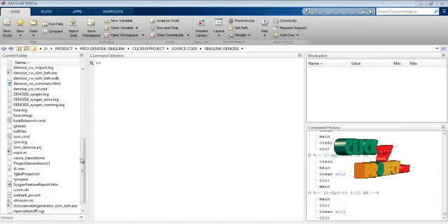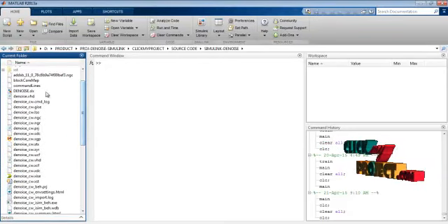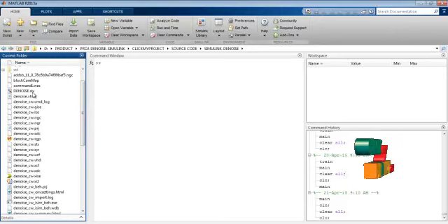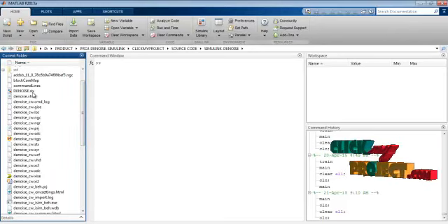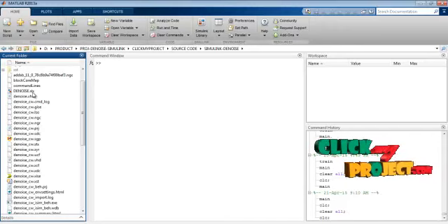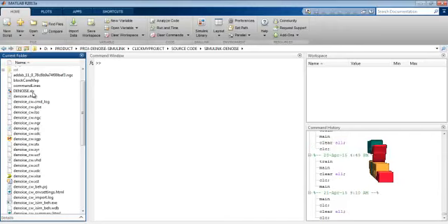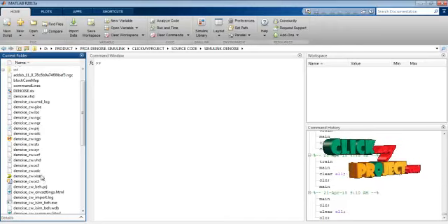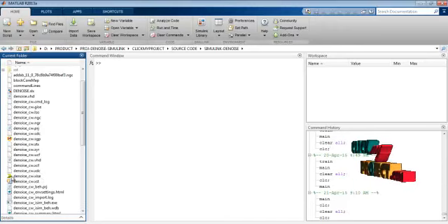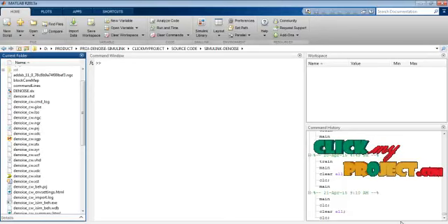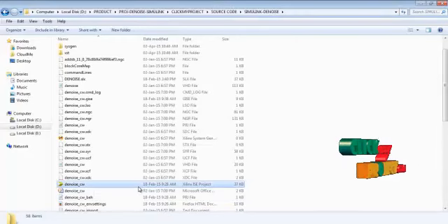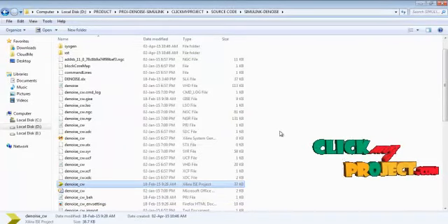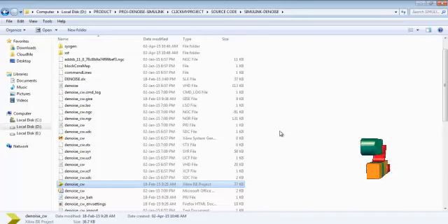Then we apply the noisy signal to the denoising Simulink design. These Simulink designs convert the signal decomposition and thresholding, then the signal reconstruction process, then apply the results for denoising processing for the Xilinx ISE project. This project converts the VHDL code and simulates our denoising Simulink designs. Then we go to the denoising conversion VHDL code for the Xilinx ISE project. This project simulates and synthesizes the result for the overall project.